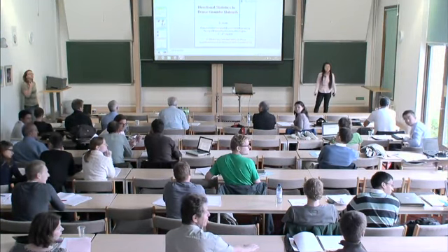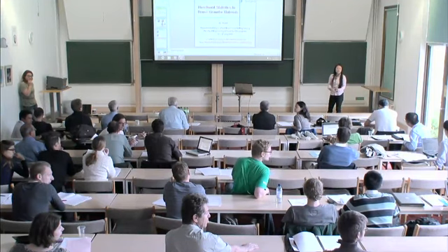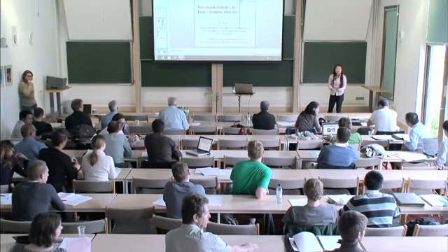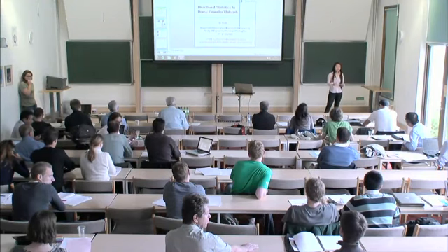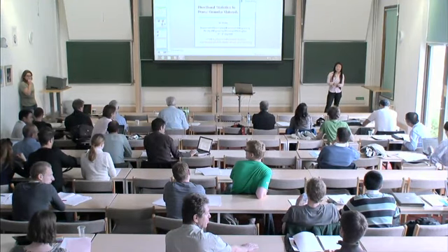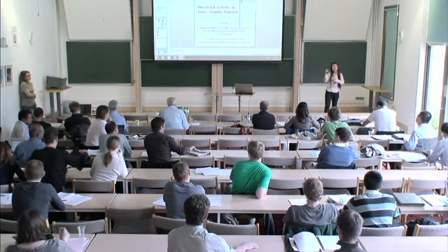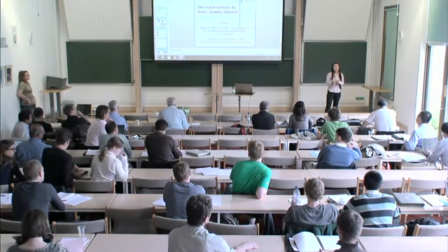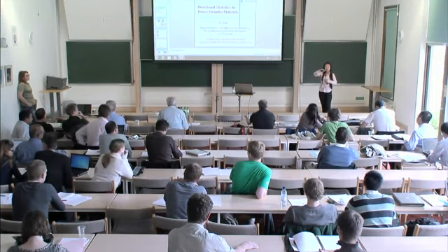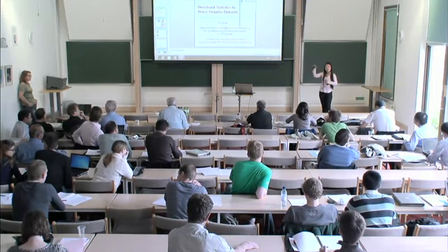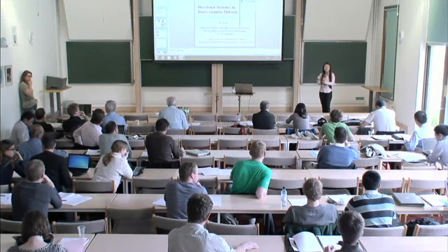This contact distribution is a constitutive component that you feed into your model. Have you considered allowing that to be a degree of freedom? What do you mean by a degree of freedom? Well, in the sense that under loading, this contact distribution itself would have an evolution, relaxation. Yeah, we have plotted the fabric evolution, including coordination number and the fabric anisotropy. I think it's the same as many soil mechanics people observe. It continually increases and approaches a constant value at a high stress level, and that anisotropy is independent of a lot of influential factors.